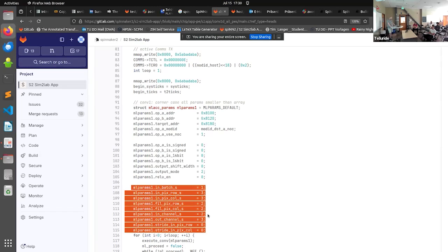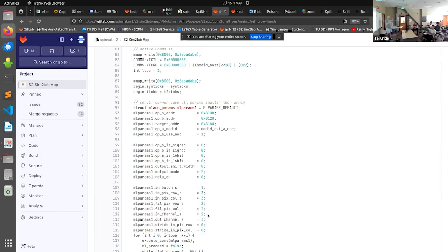One thing that's rather important is the data alignment. It's a 16x4 MAC array executing multiply accumulate operations, and some of these parameters need to align with the dimension 16 or 4. For example, for the convolution, it's the output width that needs to be a multiple of 16,